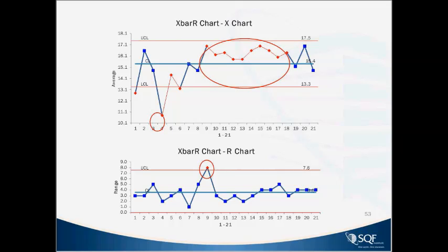You will see improvement, and when you recalculate those control limits, they will get smaller because your range values are going down, and that's a good thing. At some point, you won't get any more improvement in those settings of the control limits, and that's usually the place where you've looked at all the different things that affect variation in your process, and that's as good as you're going to get without maybe buying new equipment or something else. And that's a good thing.